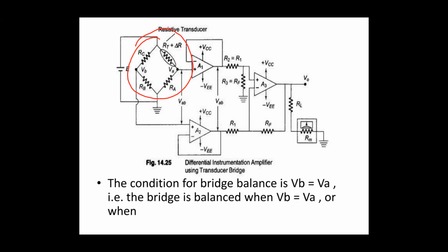Here, instead of resistances, all four arms are going to be strain gauges. The strain gauge elements are mounted on a base of a specially made weight platform, on which the external force or weight is placed. So one pair of strain gauge elements in opposite arms elongates.